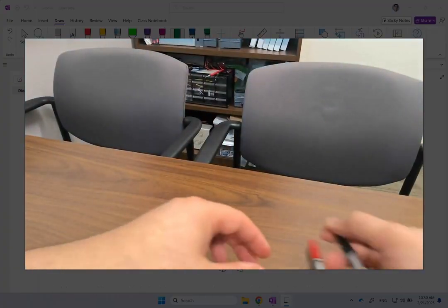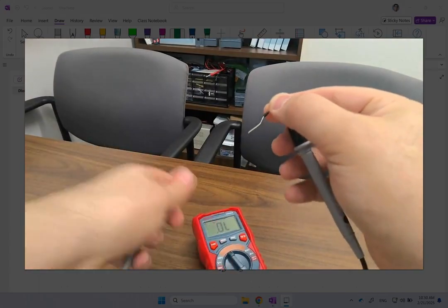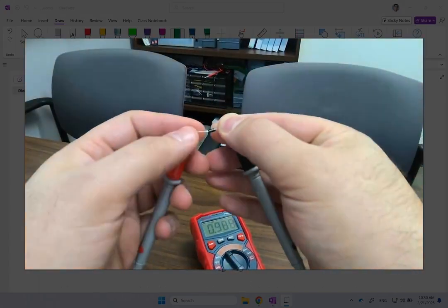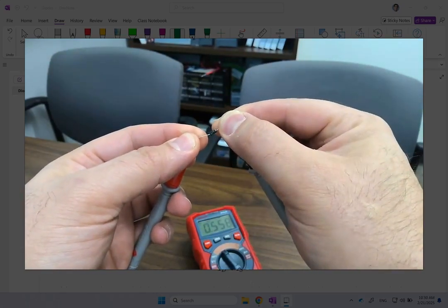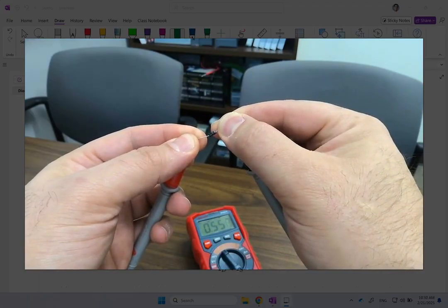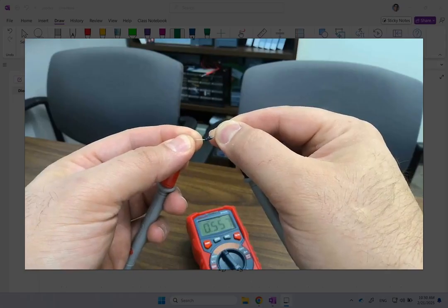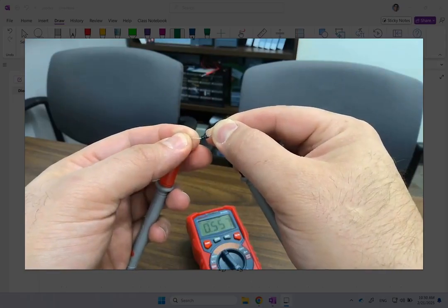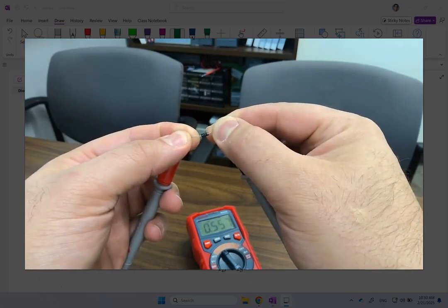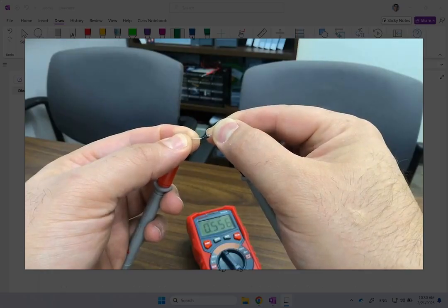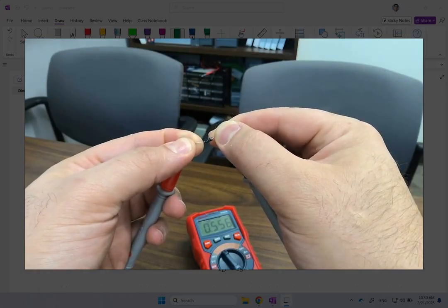The COM port is attached to the cathode, and the V is connected to the anode, and you can see the number 0.558, or about 0.56 volts. Okay, so this is most probably a silicon one, but it has a smaller typical barrier voltage than the ones that have 0.7. So this is what you can read through a typical PN diode.